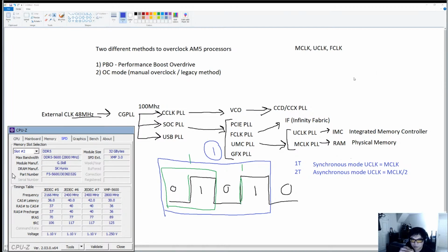On Intel, no problems with 5600, but that's because that is within the realm of Intel's official specification for 13th gen. If you look it up online, for Alder Lake 12th gen, the maximum supported RAM speed is 4800 JEDEC. Anything above that is not supported on 12th gen. So that's why it was very hit or miss. With 13th gen, 5600 is the official supported speed.